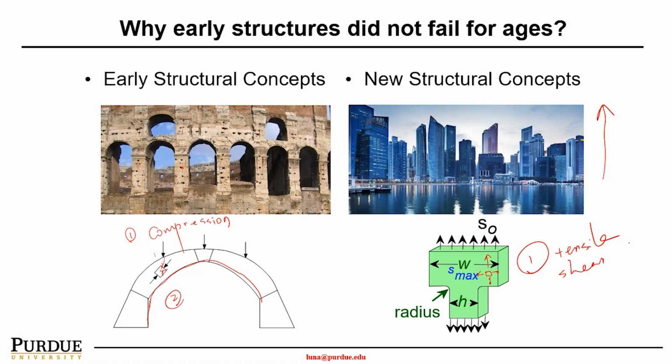shear. Number two, as can be seen, there is much complicated geometry which will lead to very sharp tips. In these corners or tips, the stress can be easily concentrated. This will create a very weak spot, or what we call stress concentration. As a result, the stress can be magnified by orders of magnitude. That will lead to a very dangerous place for the material to fail.